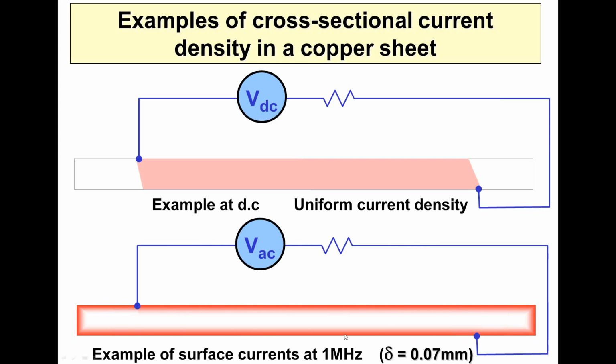So 1 millimeter thick has 15 skin depths in it, so 9 dBs times 15 is about 145 dBs. Well, that means that nothing gets through. 145 dBs is a big number of dBs. No current really gets through. If this sheet was a mile wide and we connected our AC supply across the middle of it like this, the current still has to go around the edge to get to the other contact because of skin effect. Or, if you like, the metal shielding itself.